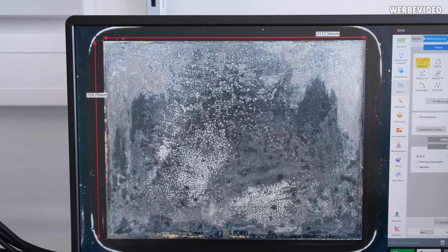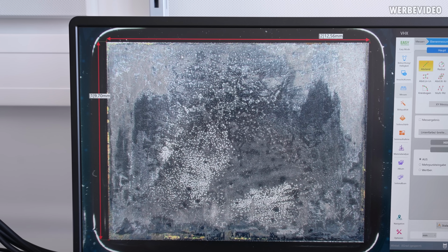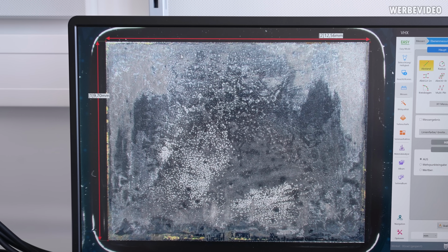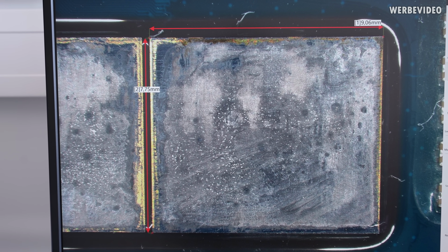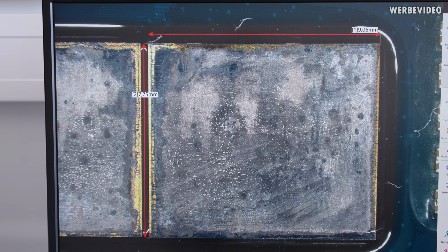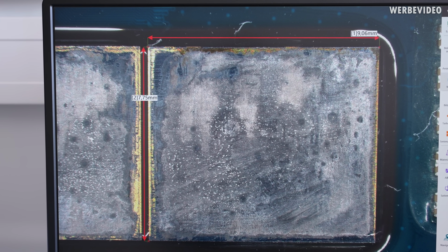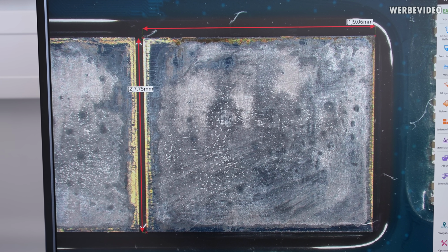And here we have the I/O die of our 9950X. It's exactly the same dimension, also 9.7 by about 12.6 millimeters. The CCD is slightly different when it comes to the dimensions, but the overall area is pretty much the same. So it changed from 6.7 and 10.4 to 7.7 and 9.1 roughly. But the overall area is about the same.